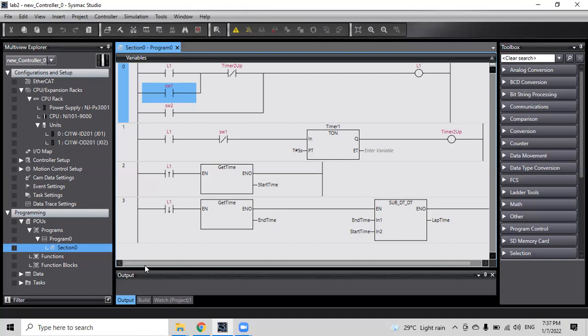So that means for this application, you've got 2 sensors, one is the starting and another one is the ending, and then you've got one actuator, L1, which is the motor to drive the escalator. These are 3 things. Then in the PLC, you have one timer, which is a 5-second timer. So when the last person steps out from the escalator, 5 seconds later, it will stop. This is the thing you need to design.